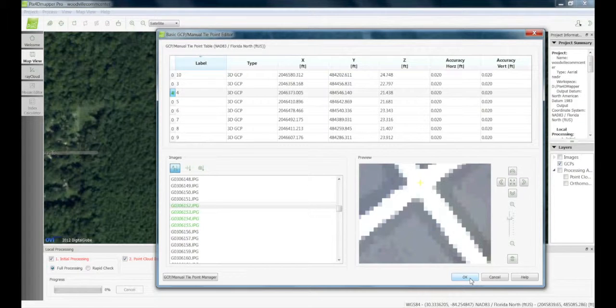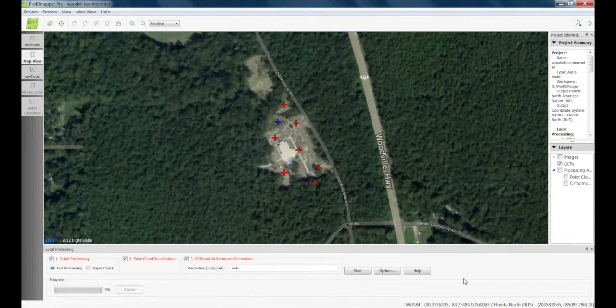And so on and so forth for each ground control point that we have listed. We'll find the corresponding photographs and identify those control points in the photographs. You can see that the red crosses are still there, but we have one blue one. The blue one is the one that we have identified photos in. Now to expedite the matter here, we're going to open up an existing file of the site that's already been processed.